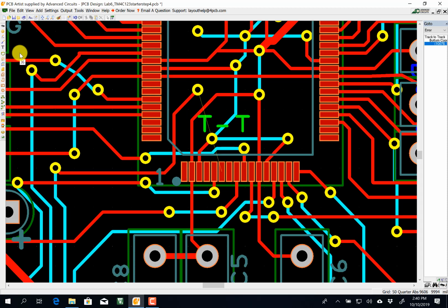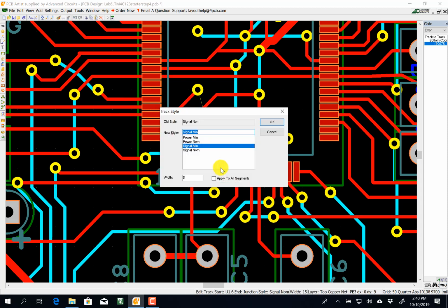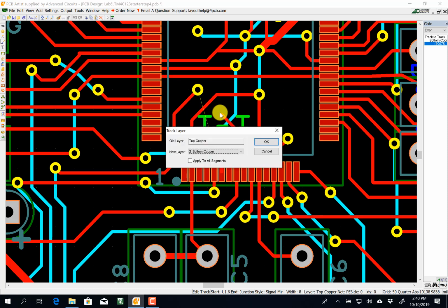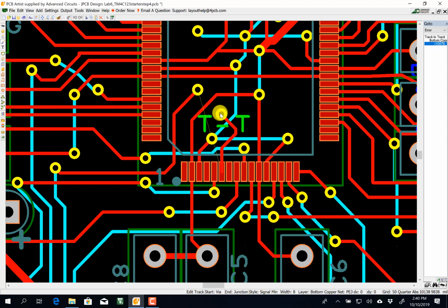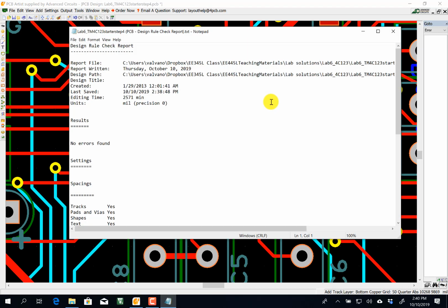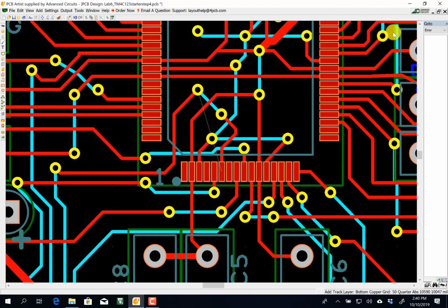So you saw I had two bottom traces that I didn't want to connect. I had them crossed. That was not good. Okay, so let's click size to small. Okay, so now I'm on the top, right? So that's good. I can go on the top up to here, and then I'll go across this one here, and now I'll change layers. Okay, and go there. Ta-da! All right, that looks better. Let's try it again. Design rule check. No errors. Okay, so now I'm done with Lab 6.